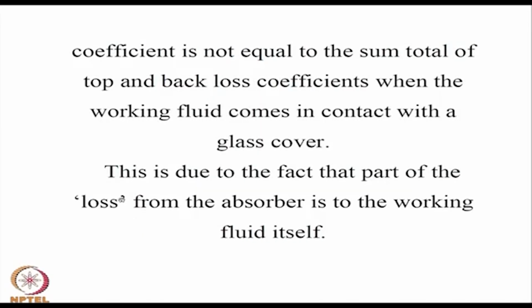So, this is what we had discussed in detail. The top loss coefficient will not be the overall loss coefficient if the heat transfer fluid comes in direct contact with the heat losing surface, this is one such case, because apparently the loss from the absorber also goes to the fluid, which is the useful energy gain.